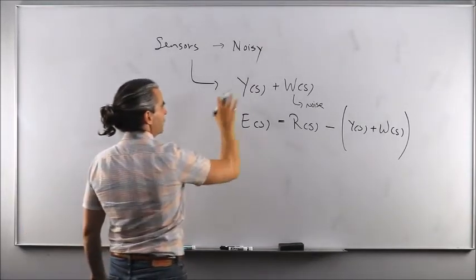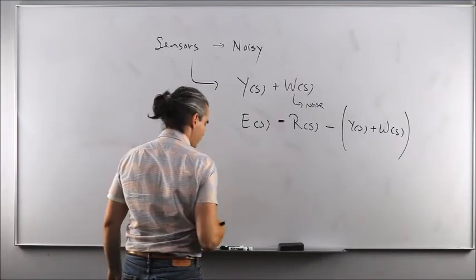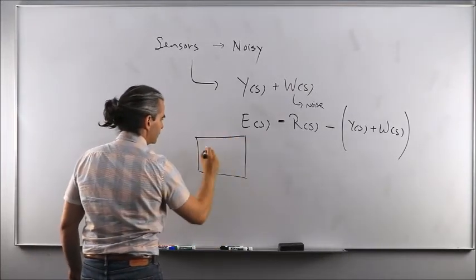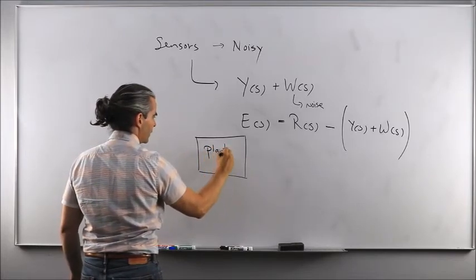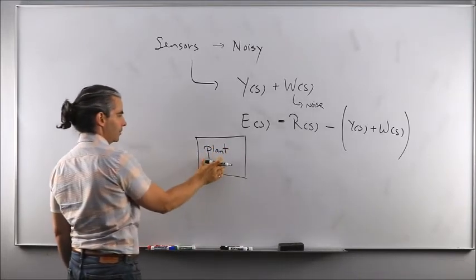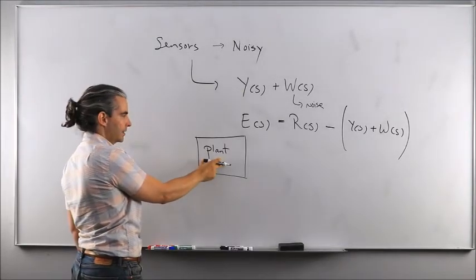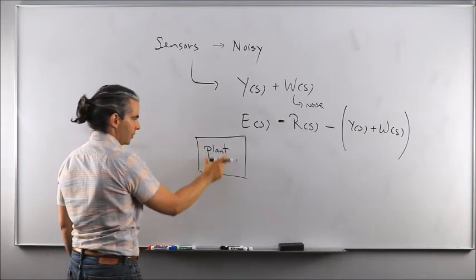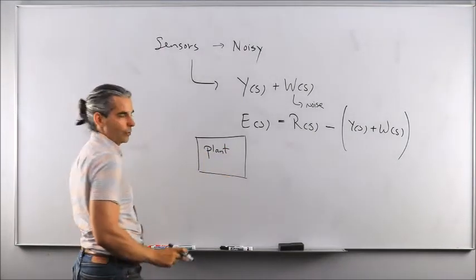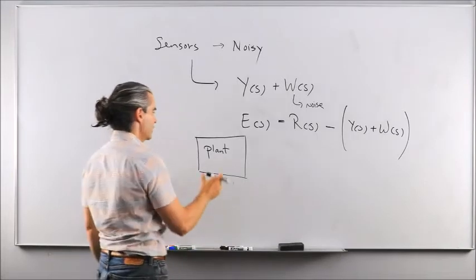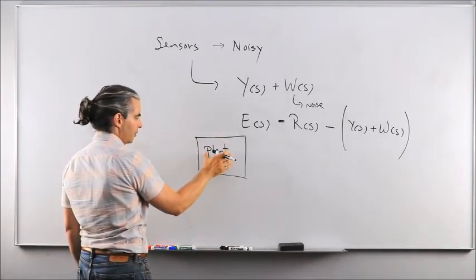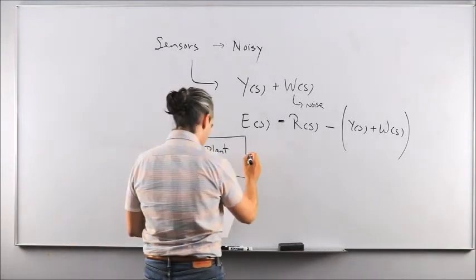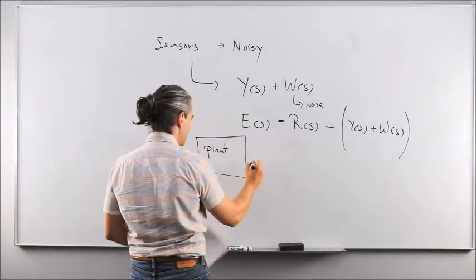So if you were to put everything we've learned thus far in a block scheme diagram, you have your plant, or in terms of spacecraft rotational motion, that would be the dynamical model of a single axis spin, okay? Because you know that everything can be decoupled about the 3 unit directions of your body fixed reference frame in terms of angles. So that could be the model of roll, and then another for pitch, and another for yaw. But again, we're doing one axis at a time, so I'm not going to copy everything 3 times, okay?